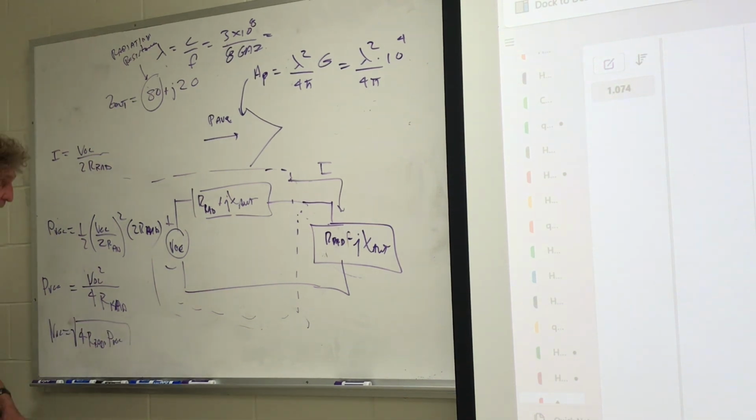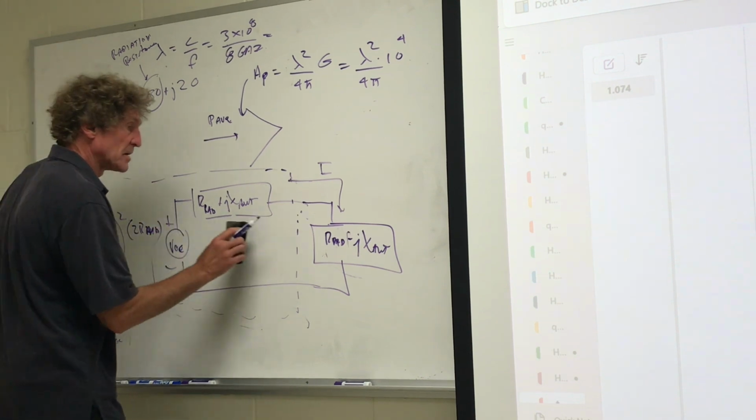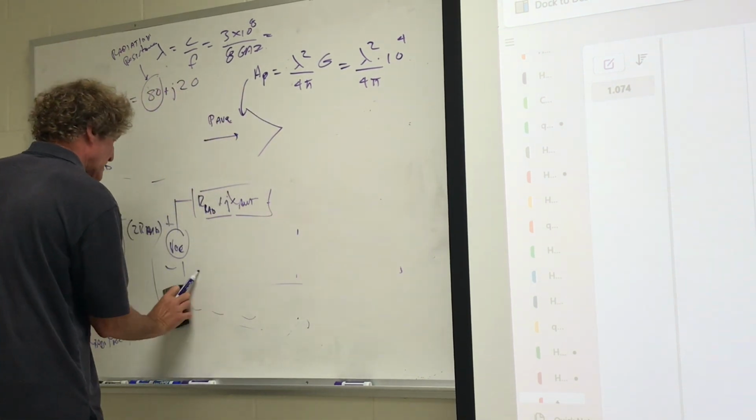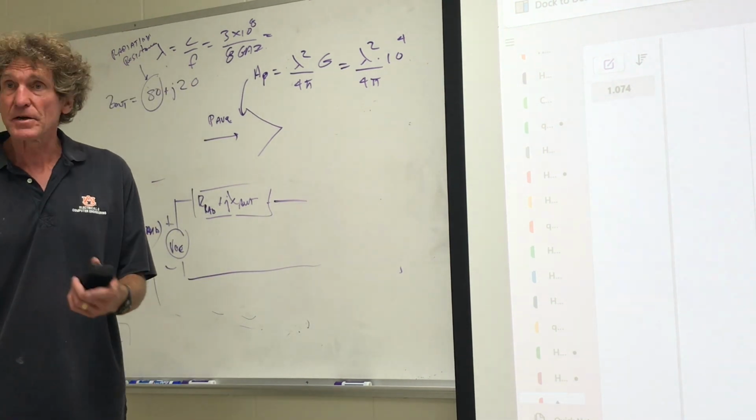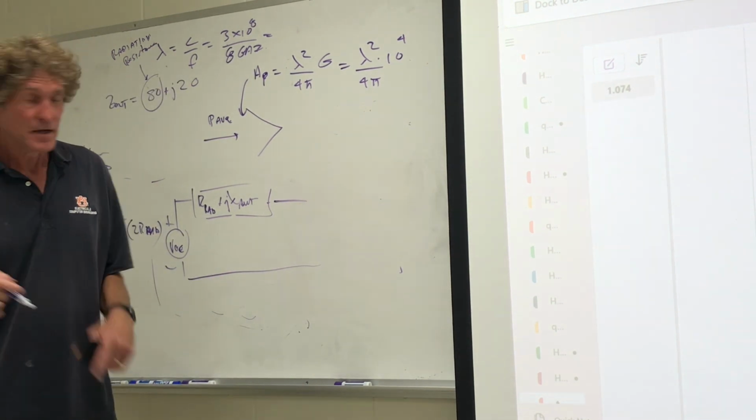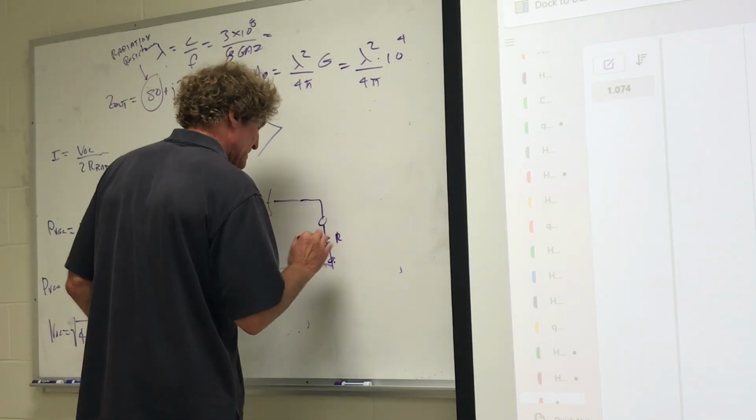All right, so what's going to happen now? I got VOC, so what do I do? Everything stays the same. What do you do with the Thevenin equivalent circuit when you have it? Now you replace open circuits, right? Once you got that, and then shorts. Now you put the load on. The load was 50, so this is 50 ohms.